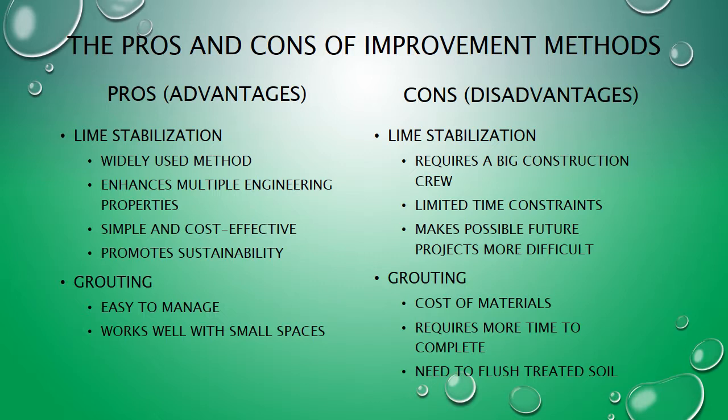Grouting benefits from only requiring a small amount of space to perform the job. This process can be relatively expensive, but the multiple improvements that come with using this method can potentially come out being cost-effective. That said, when cement grout is used, it requires ample amounts of time to set and cure with the soil. Another disadvantage is the need to continuously flush the ground treated to prevent future fractures.